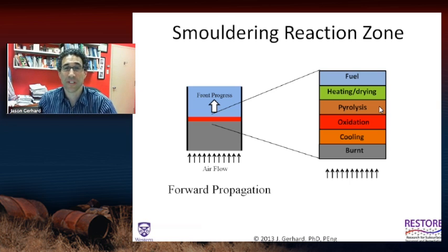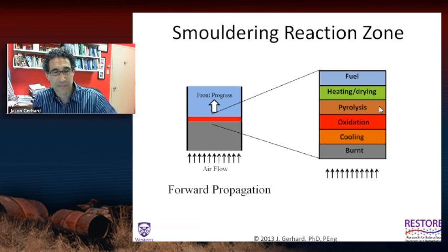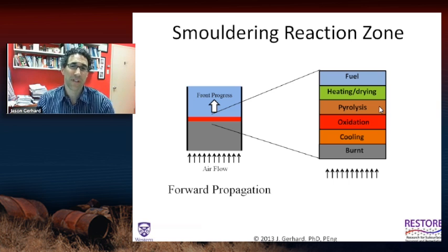And so, for example, in any kind of in situ thermal technology where they apply heat, most of the in situ thermal technology is like electrical resistive heating and other kinds of six-phase heating, where you're heating the ground continuously. You're basically applying heat all the time, and you're trying to achieve volatilization and pyrolysis. It's an endothermic process that requires continuous input of energy to break down molecules.